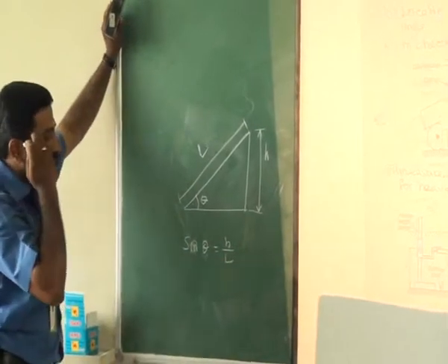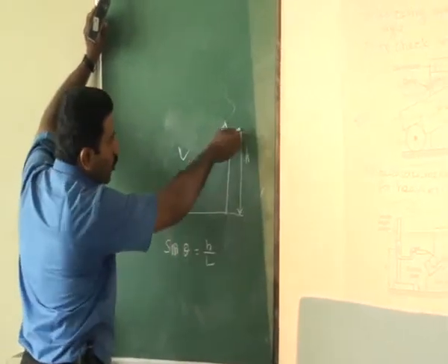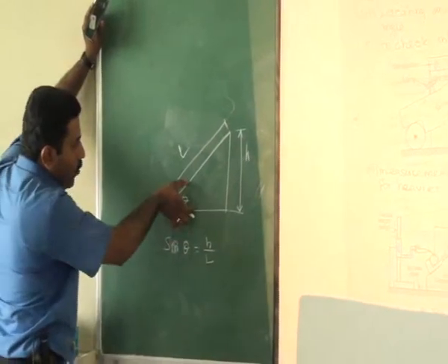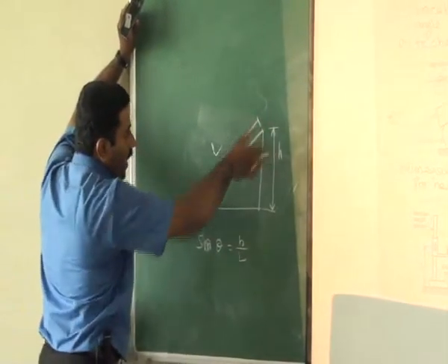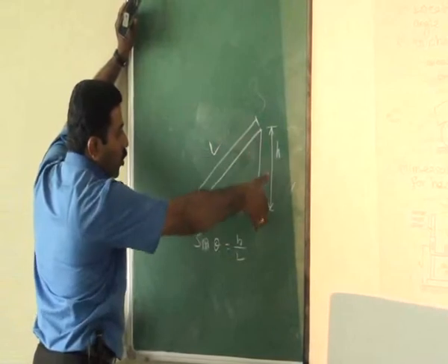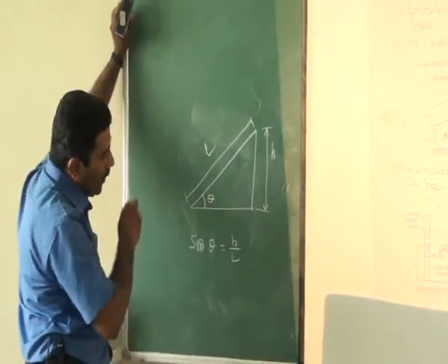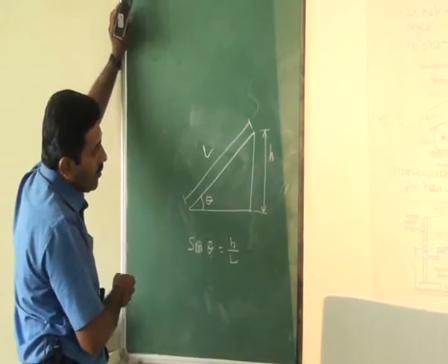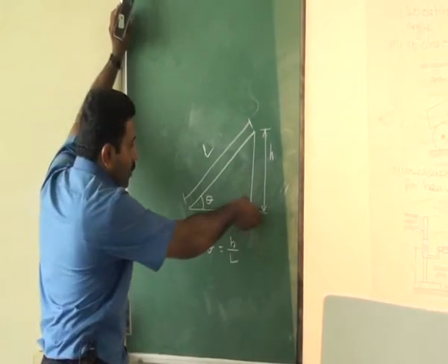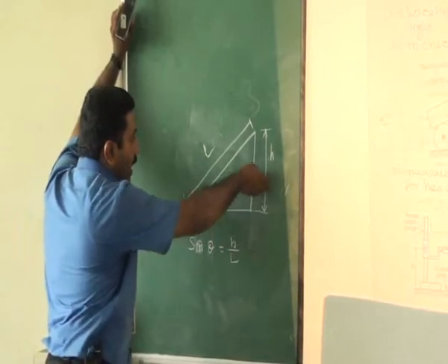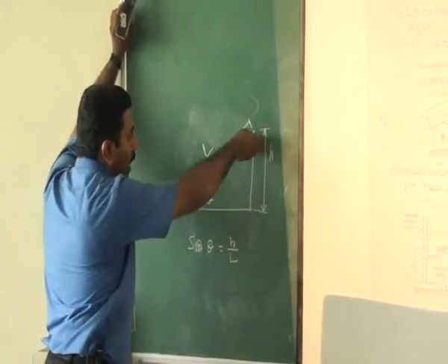So this one we have to find out. The height, how do we measure the height? This is the component one. This one is an unknown value, and we take some standard instruments. Which one is the standard instrument? Slip gauges. From the bottom we add the slip gauges according to that height.